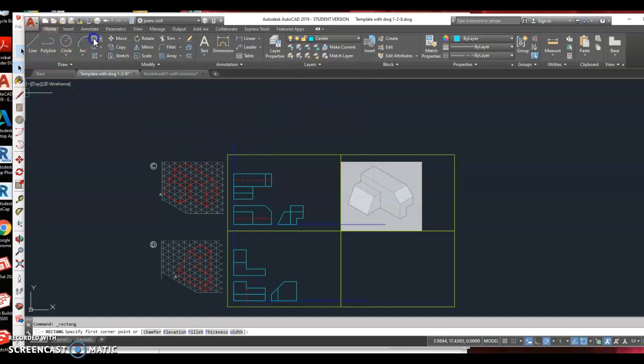And then we're going to use our rectangle tool to create 2 rectangles. One of the rectangles is going to be around these objects, right? That's my rectangle. It's a temporary centering object. And then I'm going to do the same thing for this, because this graphic object doesn't have a geometric center the way it's drawn. So I'm just going to use the rectangle, which does have a geometric center, and put it around that.